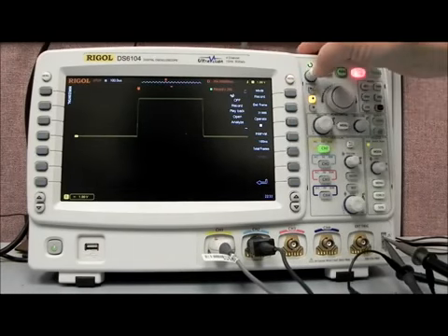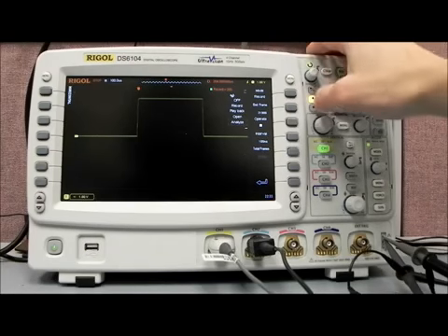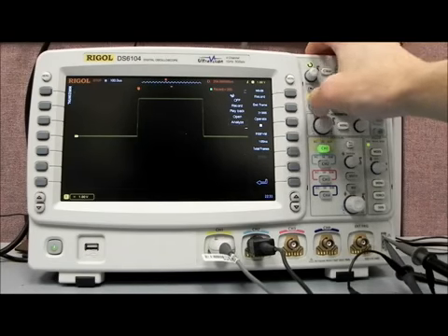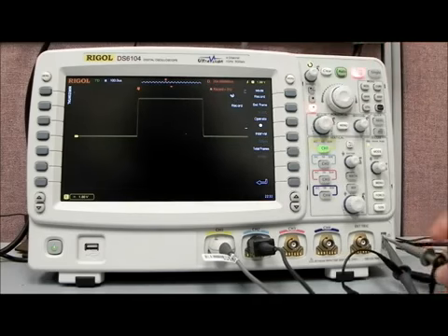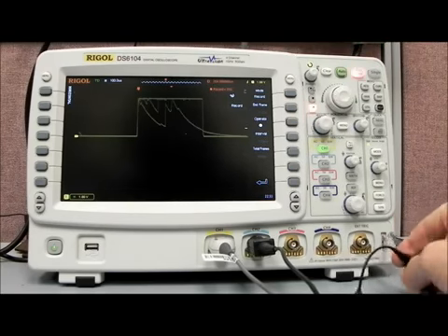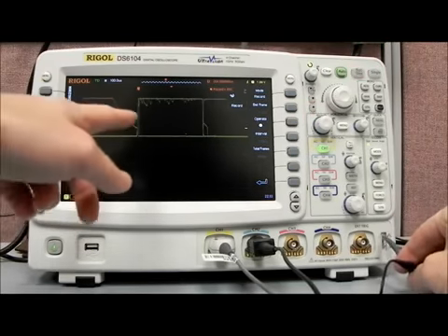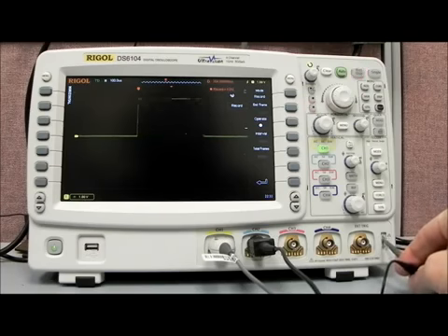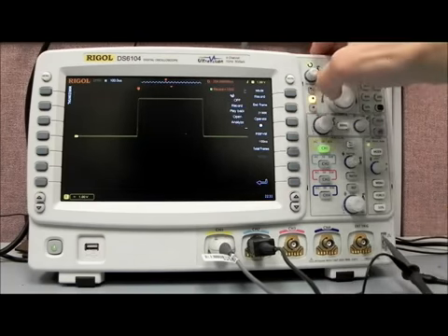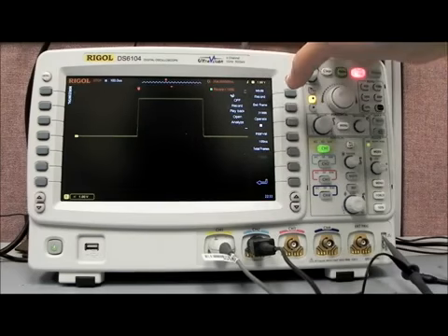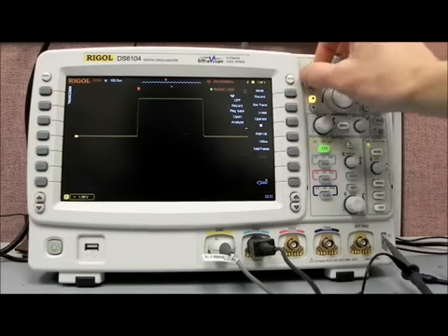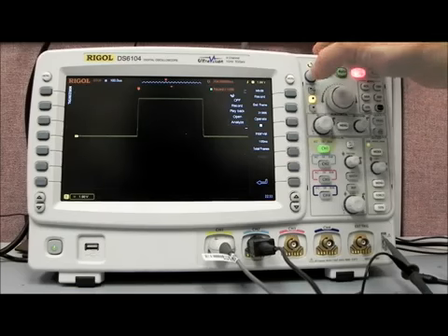Now we can also analyze that data. Actually, I'm going to record some failures, so we're going back to recording. Now I'm going to select channel 1 and just pull it off the probe compensation point, and you can see now we're getting some different values here. Then I'll place it back on, and now I'll stop. So we've collected 1,890 frames. Now let's go to Analyze.